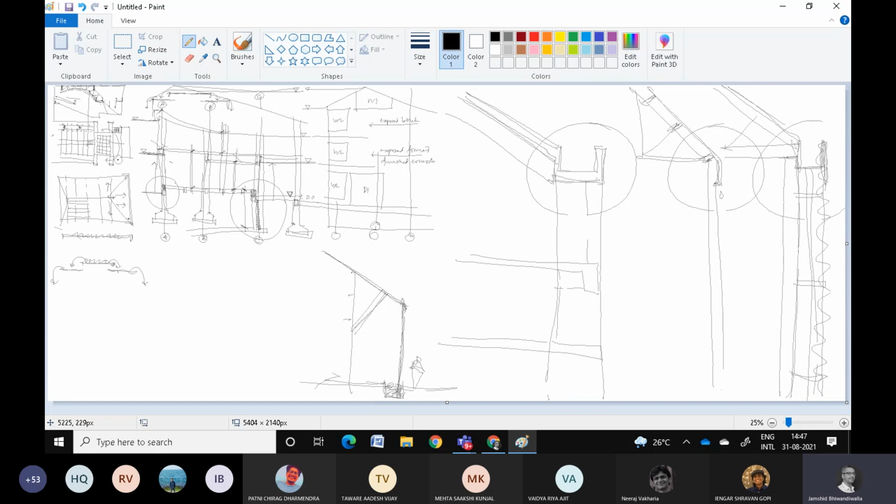If you have a metal roof, but first of all, get your idea of the metal plate. Usually if it is a masonry wall, it starts with a concrete pad. The concrete pad has a metal plate. The metal plate allows you to bolt down the truss or whatever that is there onto the wall. So suppose this is your wall, concrete column or wall, whatever, this will be your plate, allowing you to bolt the truss onto that wall.